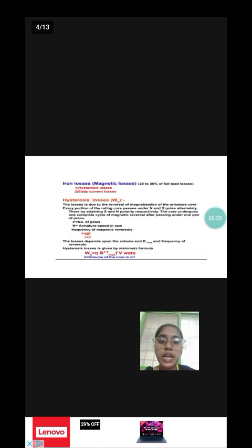First, we discuss iron and magnetic losses. They are 20 to 30% of full load losses: hysteresis and eddy current losses. Hysteresis losses are due to the reversal of magnetization of the armature core.